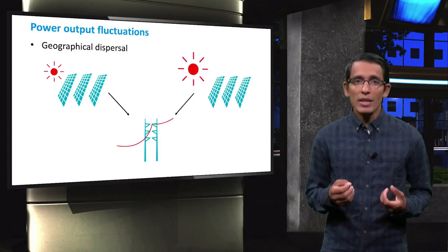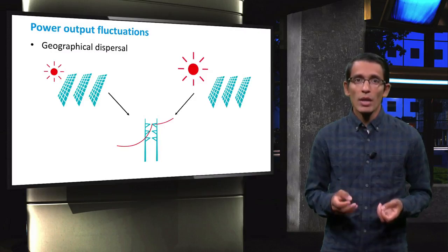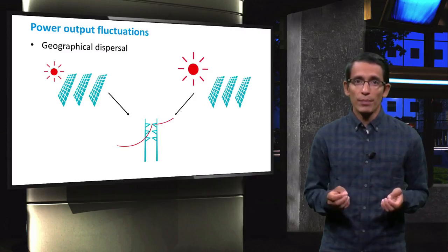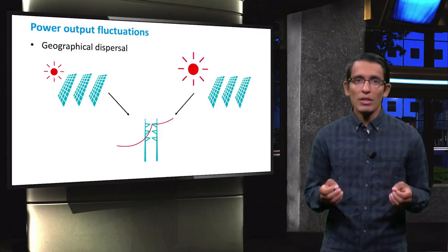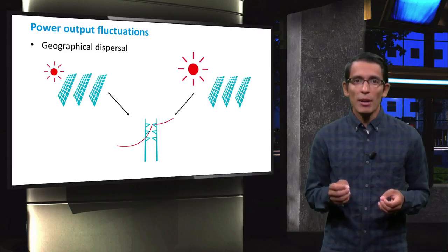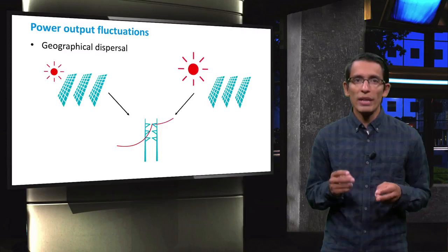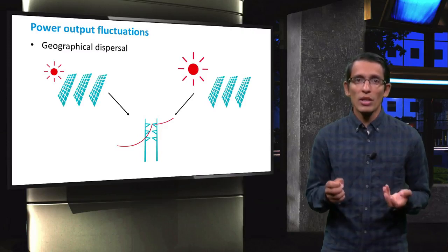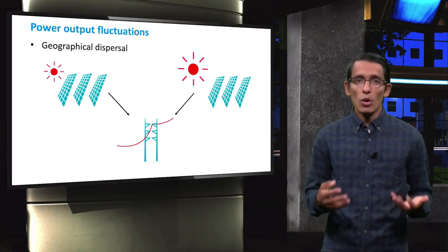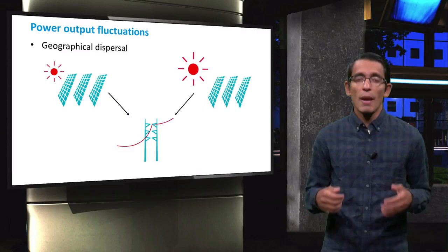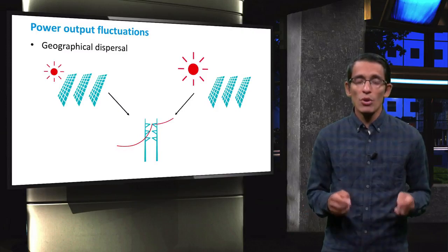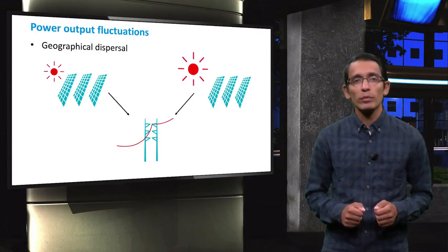In order to minimize the impact of power fluctuations, some different strategies can be adopted. For example, by means of geographical dispersal, it is possible to have simultaneously 2 or more PV farms that receive different solar irradiance or that are subject to slightly different weather conditions that can affect power production. Moreover, for longer-term fluctuations, backup generation is required in order to maintain power supply.